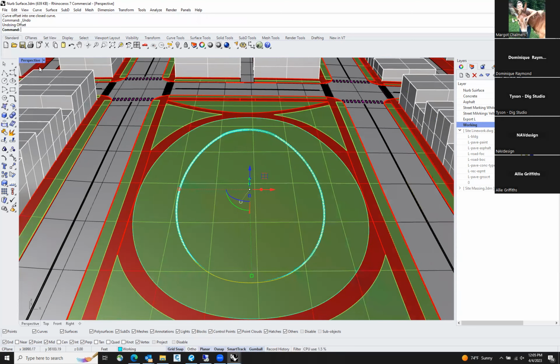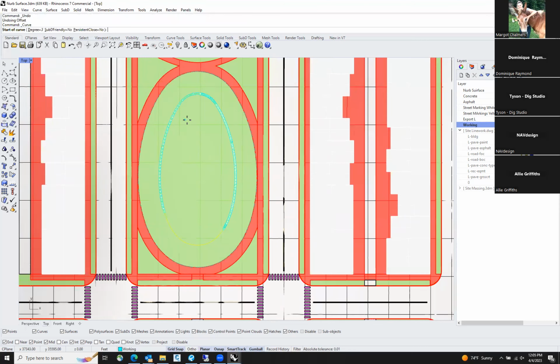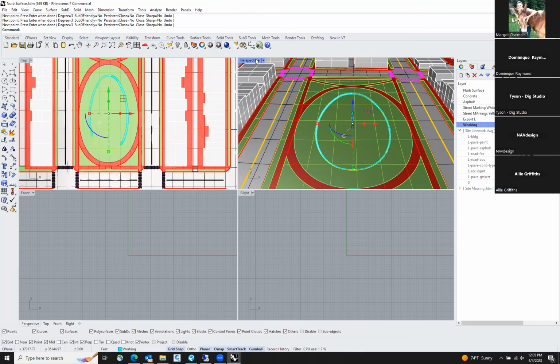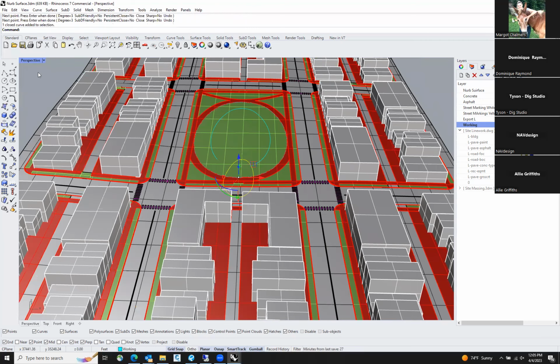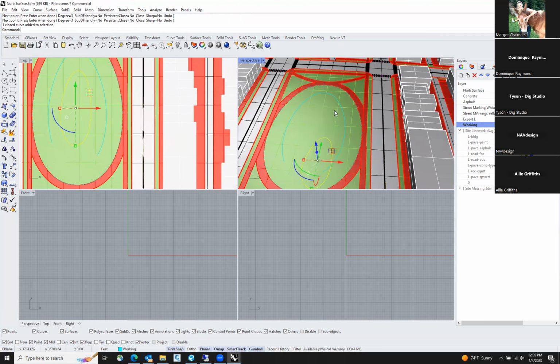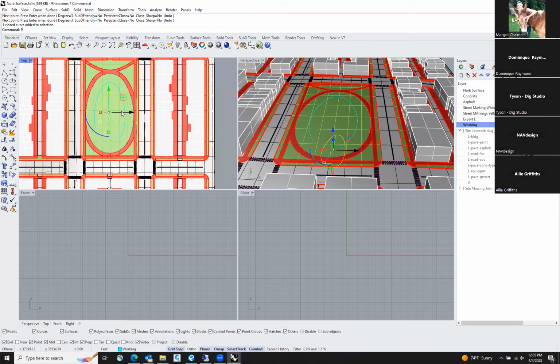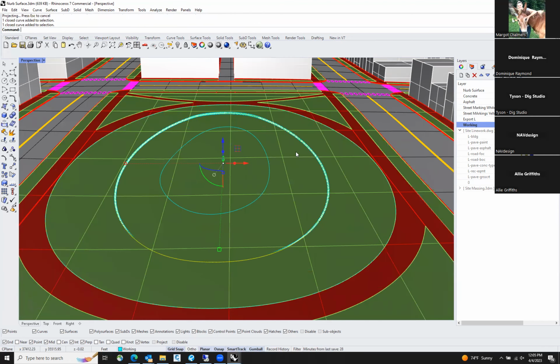Didn't like that. So I'm actually just going to go into the plan view and draw just a similar shape. You can see that shape was drawn at the 0 in the Z axis, but I want it projected to this surface, so you can type in project. And in your top view, click that. And as you'll see, it just got brought to that surface.